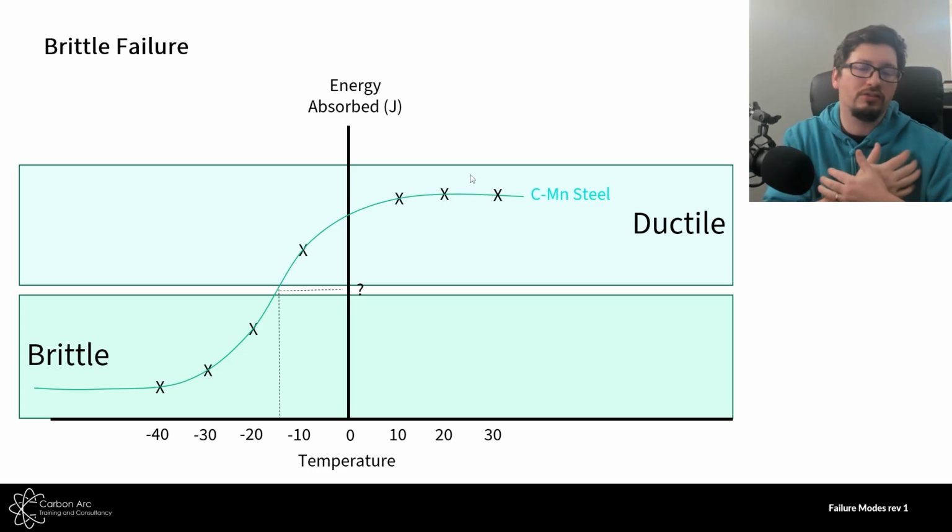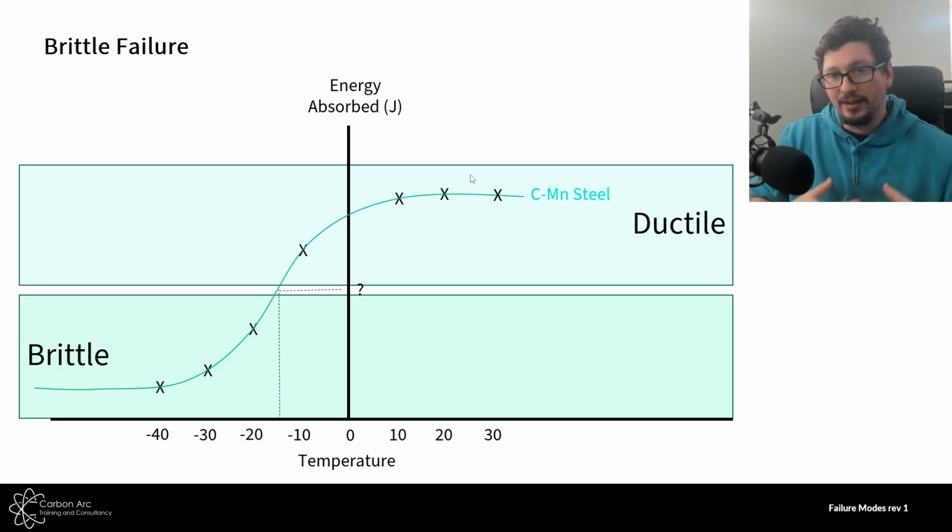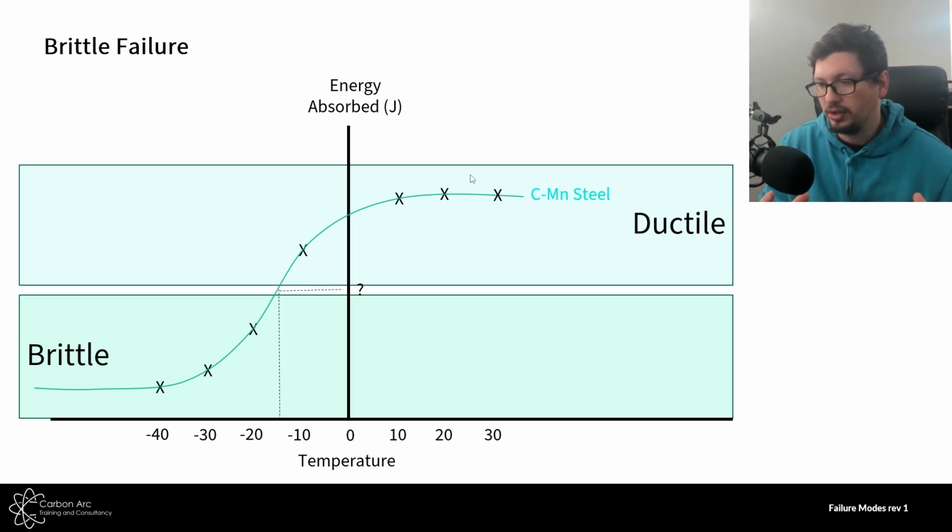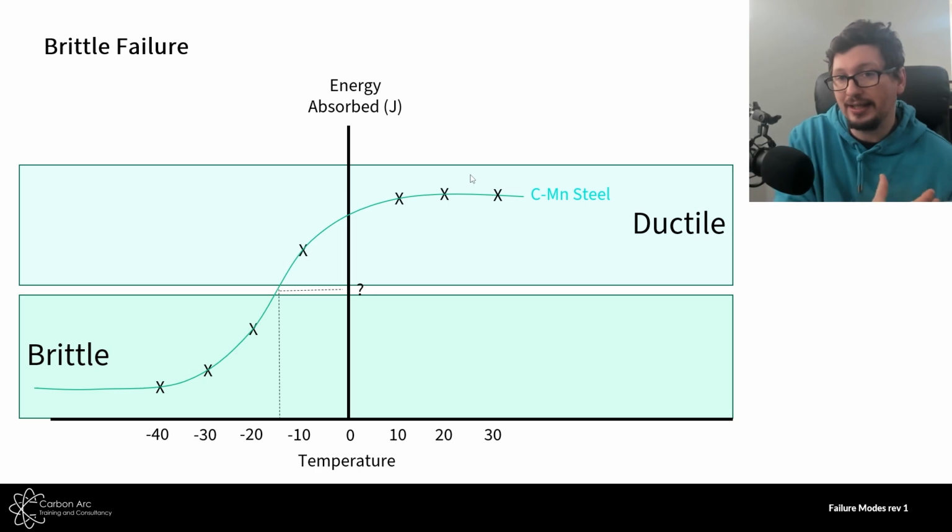We do this for all the given materials. We then weld our test samples or weld qualification samples, or PQRs, and rerun the tests and compare them directly against the base material to make sure we're still maintaining that as a minimum.